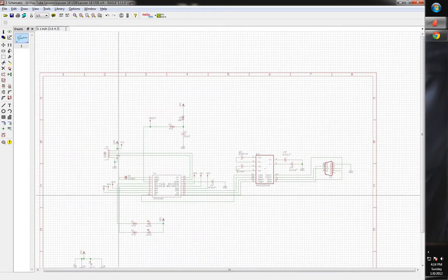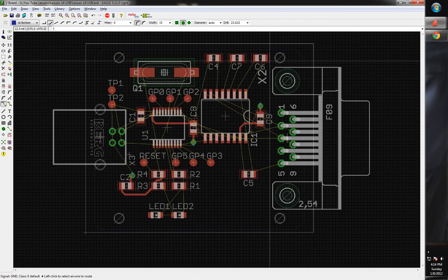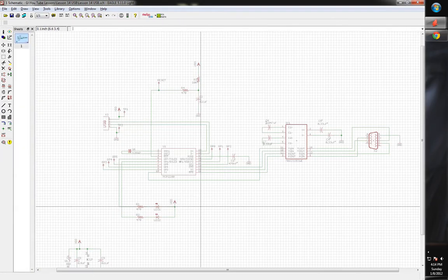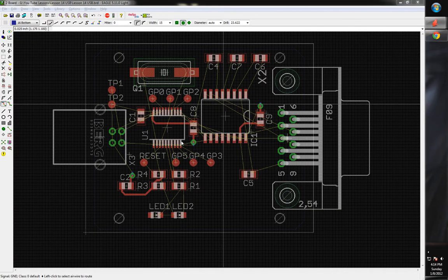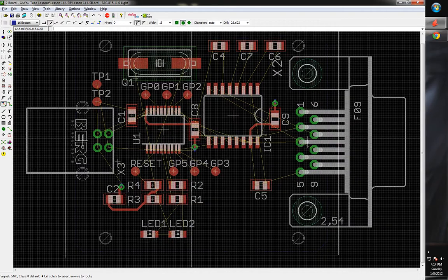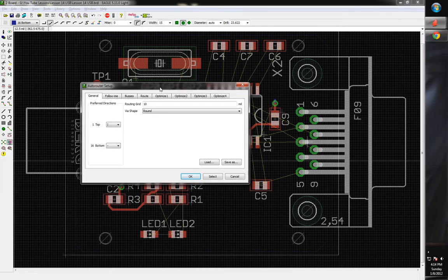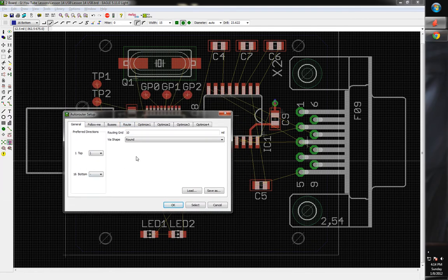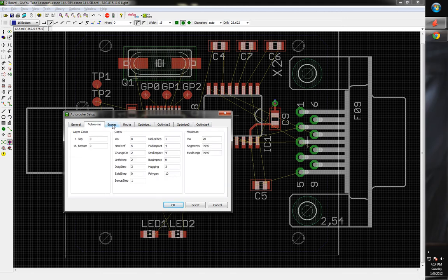So let's go ahead and set up an auto route feature while we're at it here. Make sure and save. So we're going to come over here to the auto router, which is next to the ret list command. And the auto router, how this thing works is you can save your setups. You have all these different constraints and everything that you can put in, how close you can get to different things, and the costs of putting in a via. It's pretty complicated how it actually does everything, which I haven't read a whole ton on. I just use it here and there when I need it.